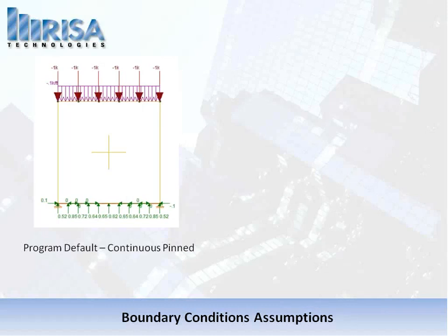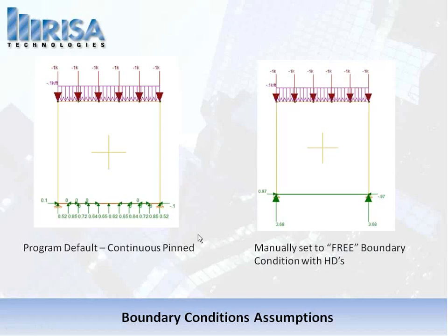So we can see from my picture here that that means that at each internal location of a plate intersection, I actually have a pin. So we're seeing a little bit of a force on this one here, in this simple wall we looked at. Now, the reason why I bring this up is because when you do a hand calc, you're looking at a wall, you typically look at each side of the wall, okay? So you think about things from each corner of that wall, especially if we're talking about lateral forces, where you would talk about the tension side and the compression side of that wall.